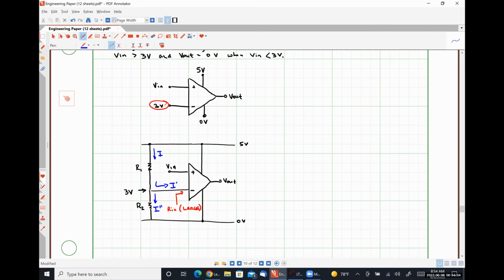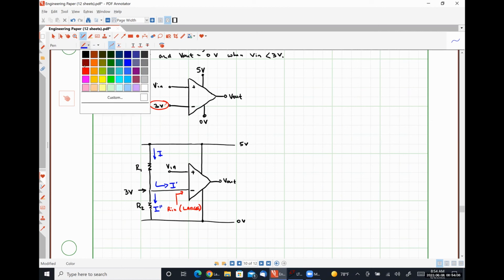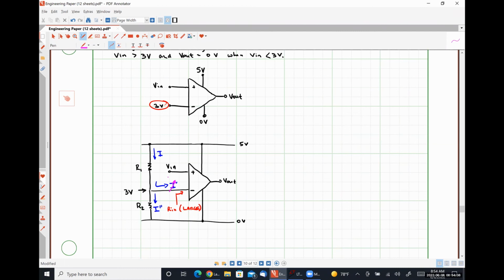Okay. I want to make this bit as close as possible to 0 amps. And I can do that by choosing R1 and R2 having a value that is much, much smaller than Rn. So effectively, this resistor network here just forms a simple voltage divider.